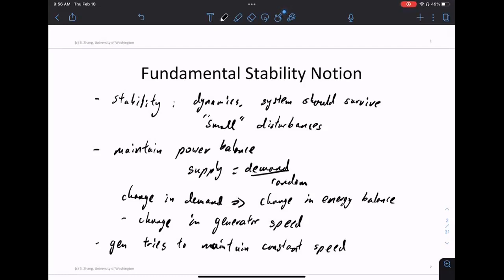You cannot isolate the system, right? You have rotating mass. So naturally, you get this feedback signal, this frequency deviation. Now imagine your system is entirely, let's say, type 4 turbines. There is a rotating mass, but that thing sits behind a power electronics conversion station. If you have solar, there's no mass there anyway. So now how do you respond to a change in the system demand?